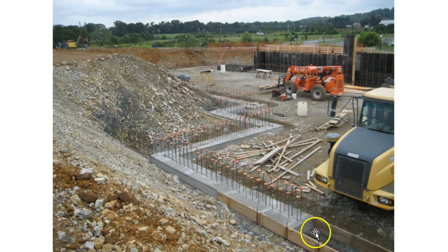Here we see some horizontal reinforcements. And here we see the formwork. So at this point they stop the pour and they're going to commence again here. So similar to these vertical reinforcements, the horizontal ones, the structural engineer will specify exactly how far they need to extend into the next footing pour, or exactly how far they need to extend up into that wall. So we see the footing in progress here.